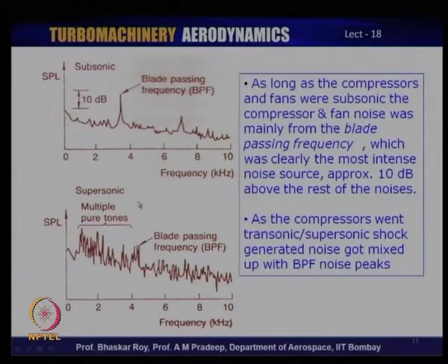In the recent compressors which have gone supersonic and transonic, we can see multiple pure tones. That means there are many of them, mainly due to the shocks that are coming out of the blades, and those shocks create noise. The blade passing frequency tone, or that particular frequency noise, is kind of mixed up or buried in all the multiple tones coming out of the supersonic compressors or fans.